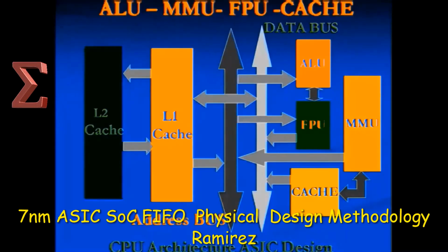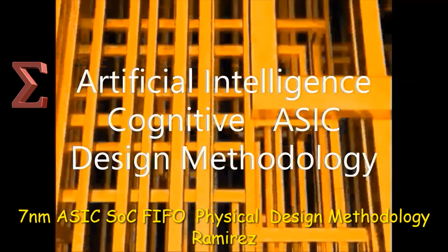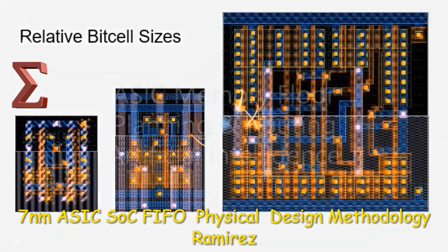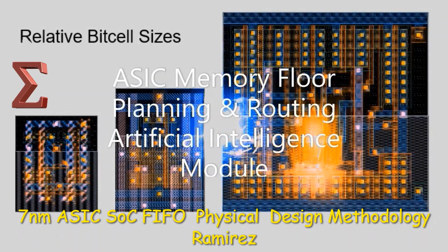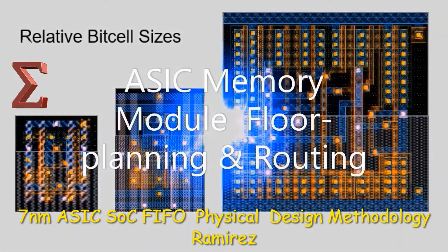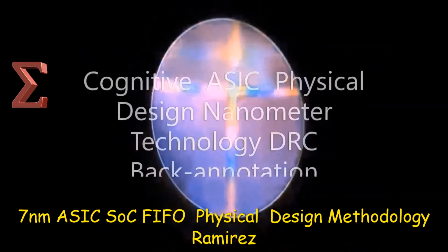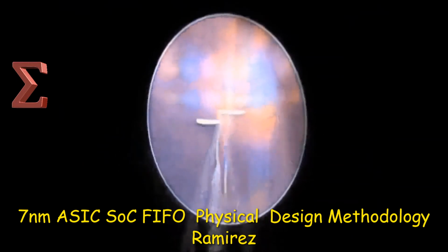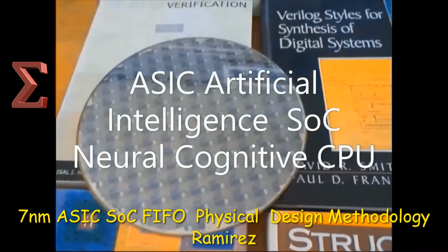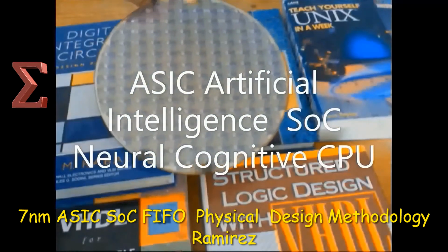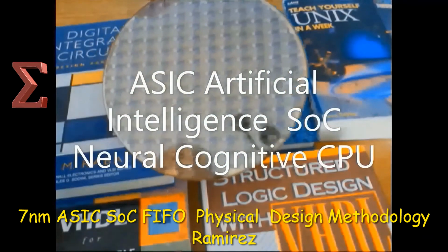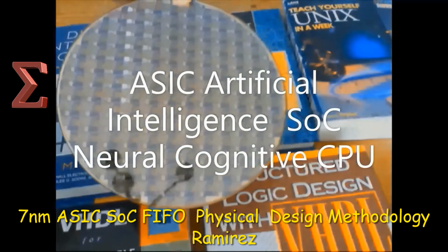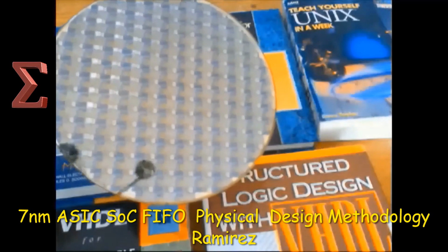On the back-end mode, it generates the SPICE models with layout views and timing models to perform DRC and LVS. You can perform this at each level of hierarchy or at the end of the hierarchy, and it simulates power and delay, and it can also be back annotated.